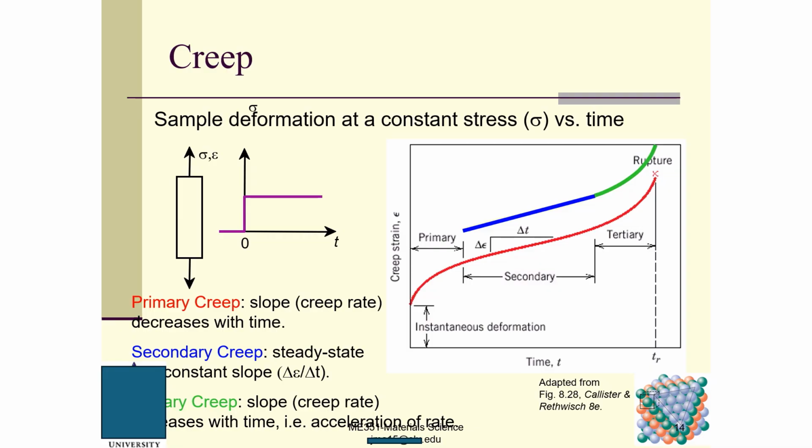And we talk about our next important concept, creep. Right? So this is creep. And what is creep? Also, in the mechanics of solids lab, we are going to do the creep testing. Creep means that at a certain temperature, if given a load, even though the load remains constant, the strain keeps growing. This is called creep.